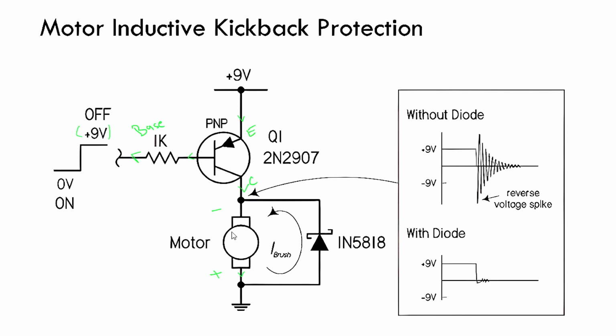To oppose the change in current, that reverse polarity forces this transistor to flow current again, like it was previously. Because of the generation of negative voltage here, suddenly high voltage spikes come here and force this transistor to flow current again to run this motor. Lots of electrons and spikes are created, and that spike can damage this transistor if there is no diode here.